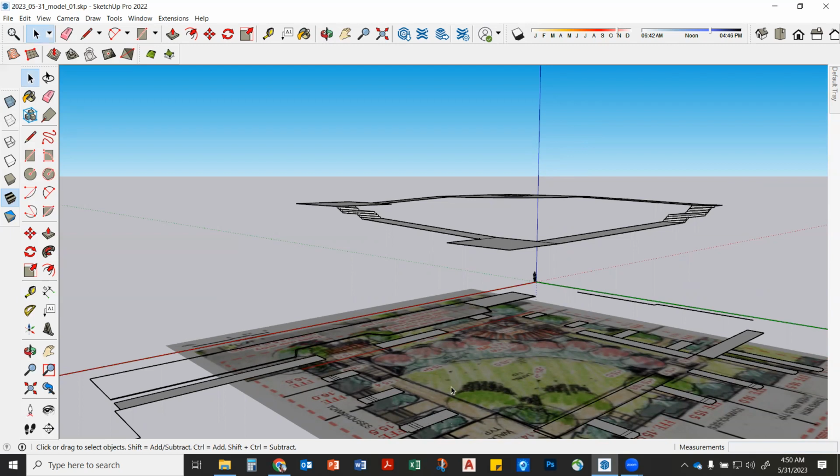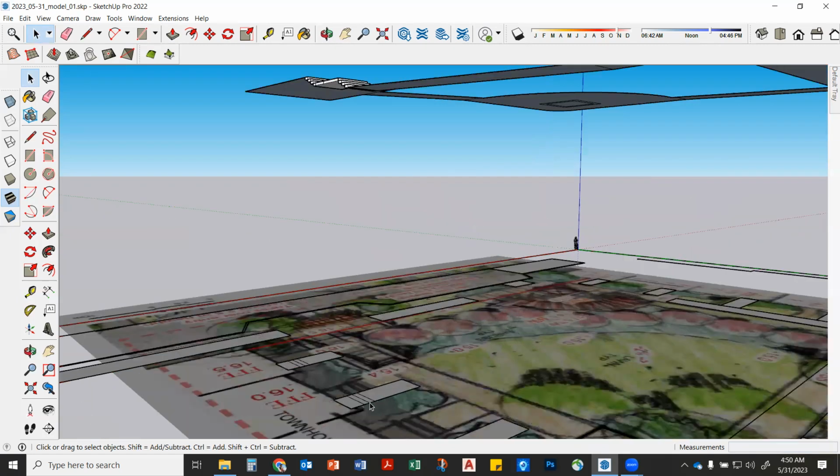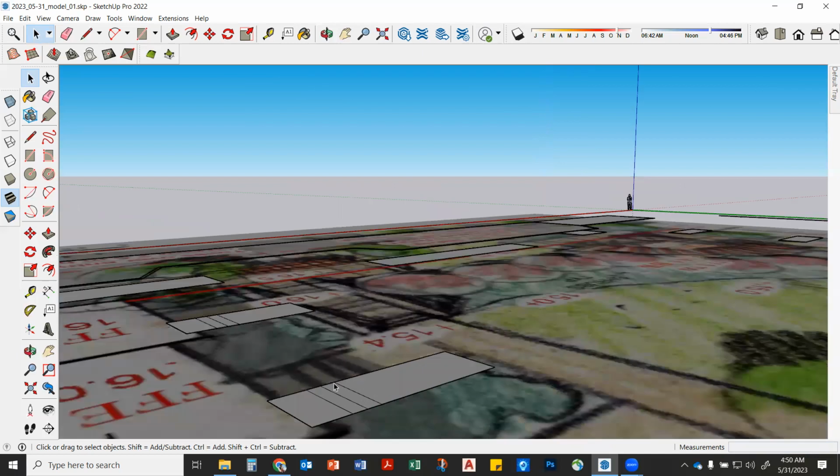These steps. You have a landing along. Well, and technically, you should have a level spot everywhere there's a landing, or 2% landing. But in this model, I generally don't even do that. All I do is from my stairs, I'll pull this up and then from my stairs, I go click, click, click, click, and I do from contours.